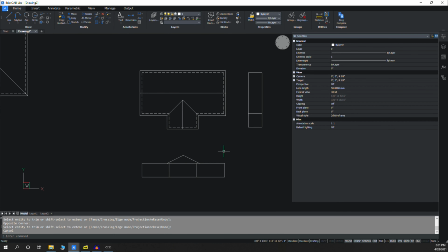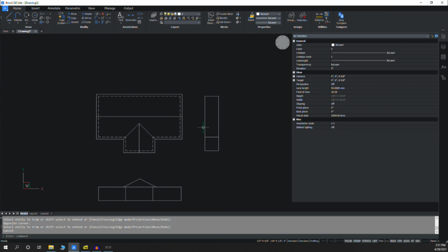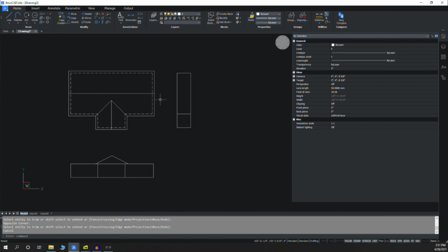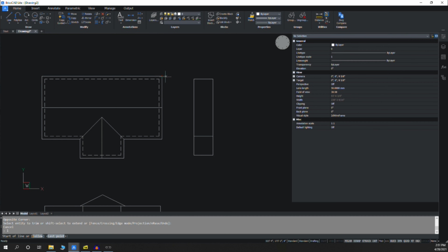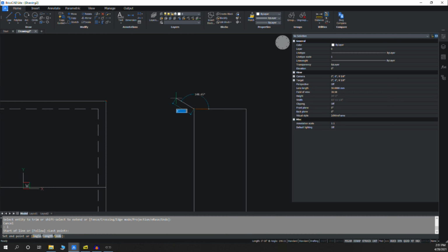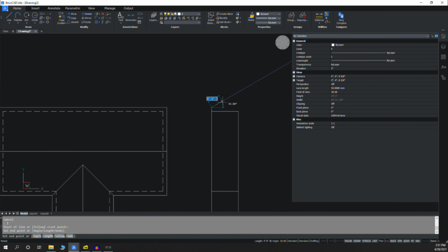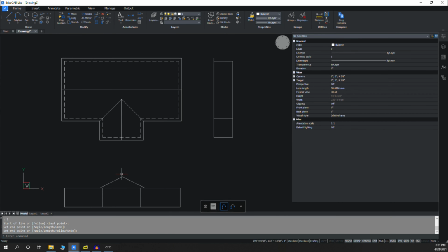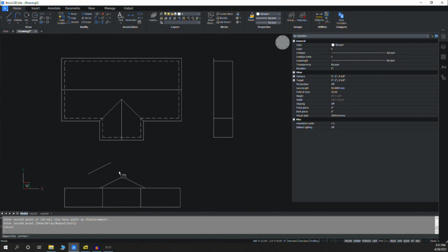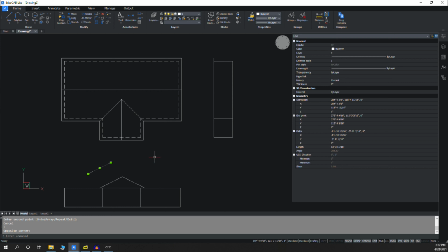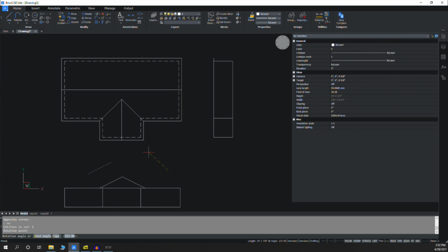We still have to draw this main roof, and from this view I can't tell how high it is. So what I'm going to have to do is go to my other elevation, and this is common. You're kind of flipping back and forth between elevation views. So we draw our eave here. I shouldn't have deleted that line, but I can actually grab it. I'm going to copy because this line's at the right pitch. I'm going to rotate it.